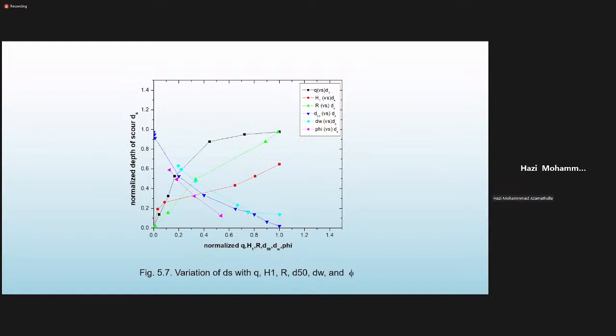And this one is common sense, right? If water jumps from a high head to the tailwater, scour will happen due to the head. Scour depth is also high due to energy, right? But here you can see that for scour depth, some parameters are inversely proportional, some are relatively proportional. You can see here, the green one is bucket radius, which is inversely related.